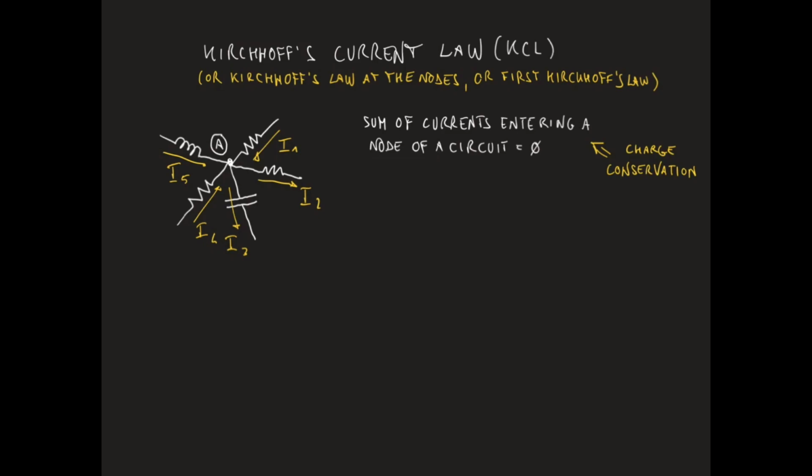In stating Kirchhoff's law for currents, I use the expression algebraic sum of the currents. By algebraic sum of the currents, we mean the sum of the currents each with its sign. The sign of the current will depend on a preliminarily adopted convention on the current direction in the circuit. For instance, we can assume that the current is positive if it enters the node.